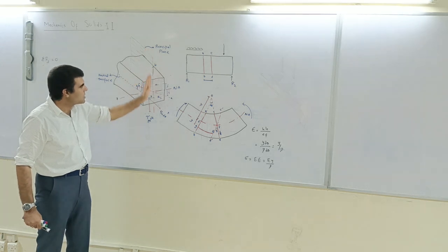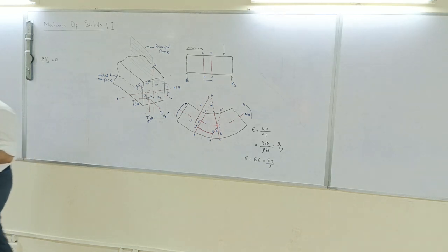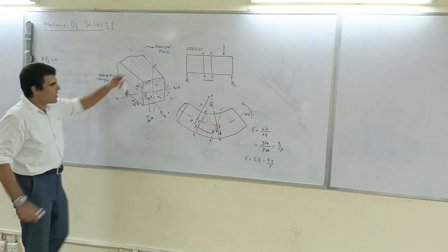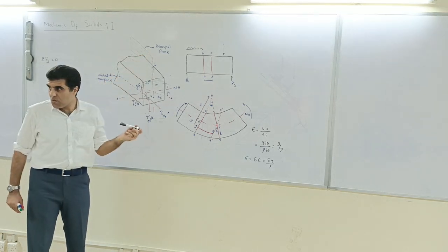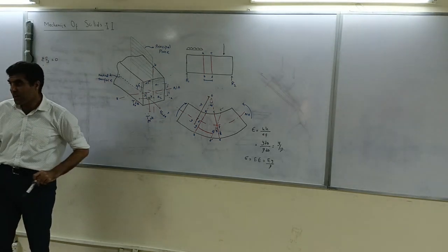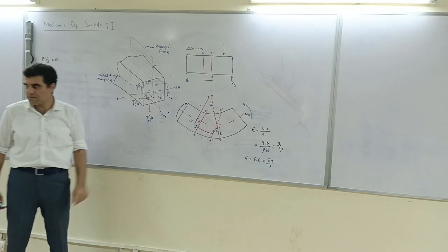We have all the forces in the y direction must be equal to 0. So what do you get from summation of Fy is equal to 0? What is the significance of this? The significance is that summation of Fy actually gives you the shear.